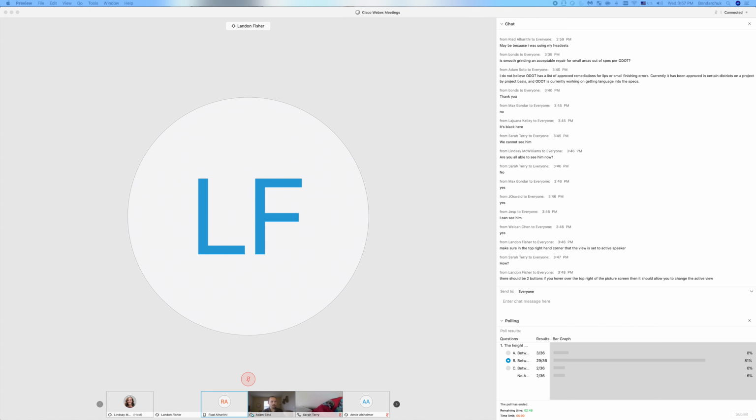If you put the design control number, it will prompt you for the design value. If the design value is, let's say, 2.1 on the cross slope, and you put 2.6, it will pass because the tolerance is 0.5%. If you put 2.7, it will fail. I'm not sure if that was covered during today or not. Yeah, Landon did cover that during the form. Great, thank you, Landon.